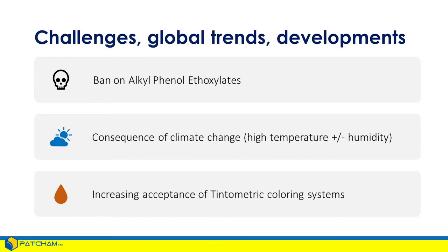This is where, for any chemistry of paint, the paint supplier manufactures 3 different bases: a regular white tint base that's intended to be tinted with 4 ounces of colorant to finish making the paint, or a neutral base that takes either 6 to 8 ounces of colorant, and then the deep base, which is designed to take 12 ounces